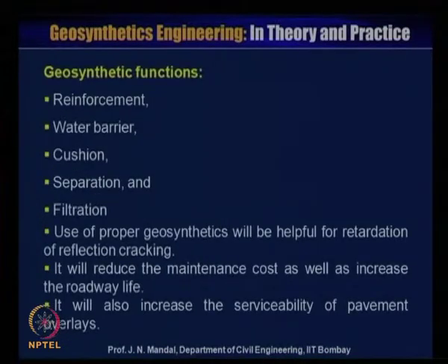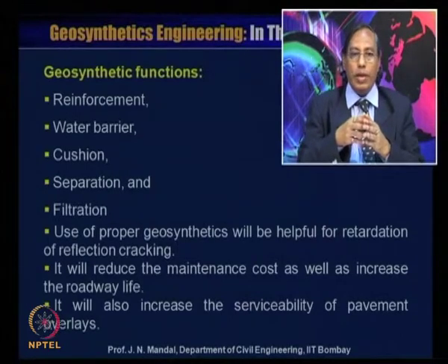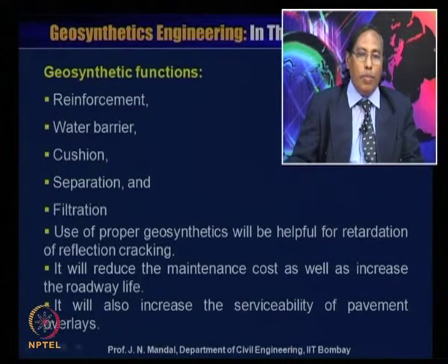So, the main function of the geosynthetics is that it acts as a reinforcement and also as a water barrier, cushion, separation and filtration. The use of proper geosynthetics will be helpful for the retardation of reflection cracking. It will reduce the maintenance cost as well as increase the roadway life. It will also increase the serviceability of the pavement overlay.